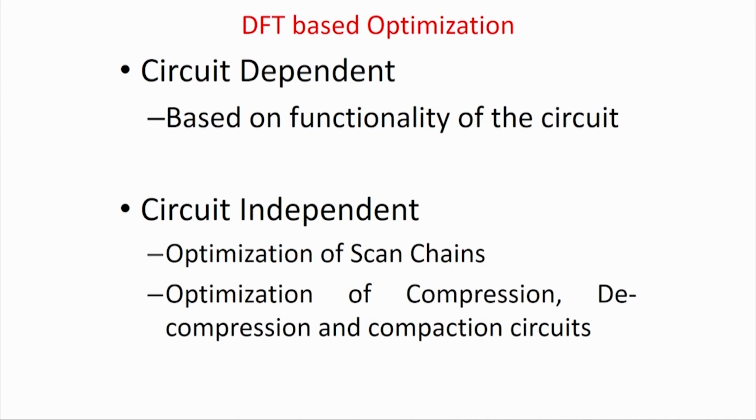That is, given a circuit and its functionality, I want to put some kind of special test pattern generator inside the chip which can help you to test it. But it will be very much dependent on the circuit functionality or the type of circuit under test. So it is totally based on a design-to-design and case-to-case basis. There is no algorithm as such, or I can say there is no generalized architecture to do this. It has to be handled case by case by the designer and the test engineer targeting that particular design.